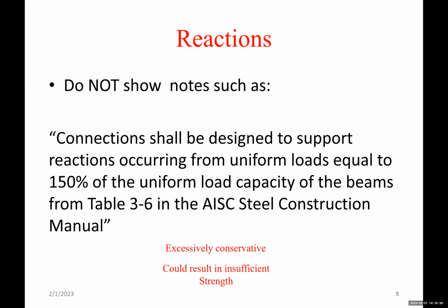Do not show notes such as "connections shall be designed to support reactions occurring from uniform load equal to 150% of the uniform load capacity of the beams from table 3.6 in the AISC construction manual." So these notes used to be, maybe still, I don't know, on the drawings by structural engineers.